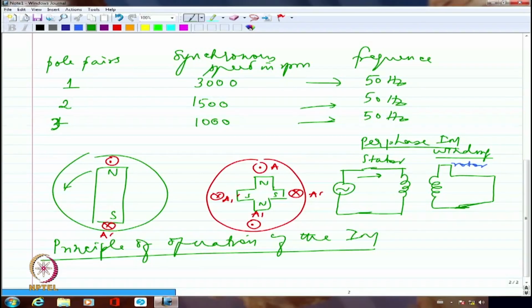We talked about this. In the transformer, if I short circuit it, I will have huge current being drawn if I am not going to include any load. Simply short circuit it. That's it. So in that case, I am going to have a huge current drawn. No wonder an induction motor normally draws a very large current during starting. Whether I like it or not, induction motors draw a very, very large current during starting because it is as good as a short circuited transformer.